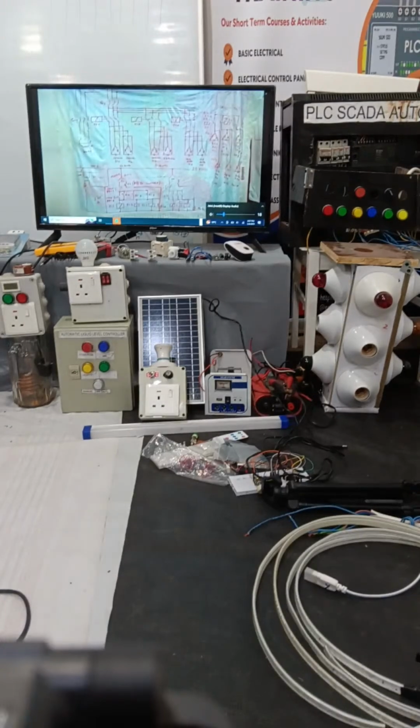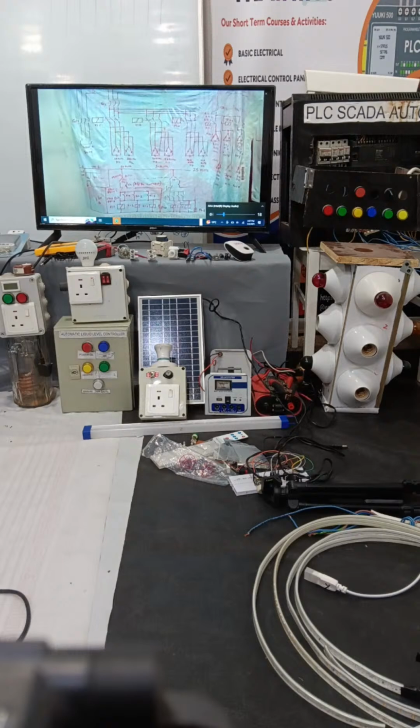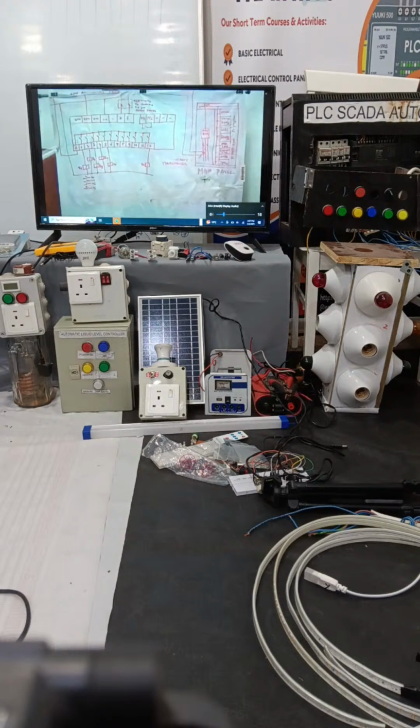Now in the next chapter we will see the wiring diagram of the controller. This is a typical diagram of a controller. Here our supply voltage is 230 volt control supply. This controller has options for 400 volt, 230 volt, 110 volt, and 0 is common. We have to apply the voltage depending upon availability.